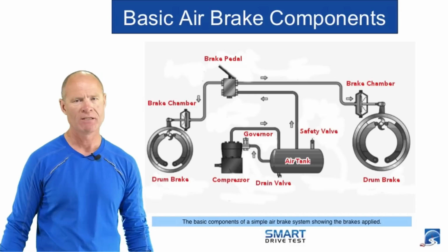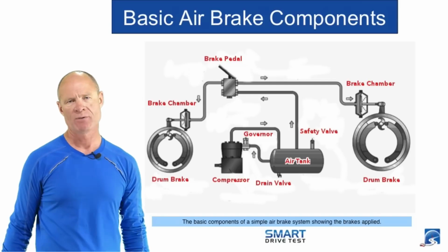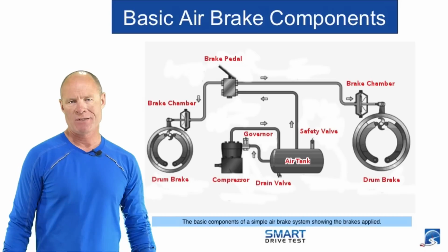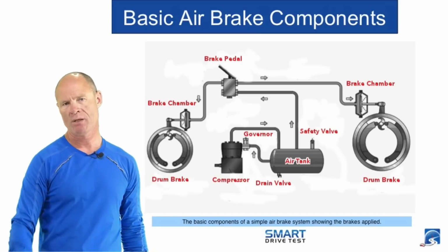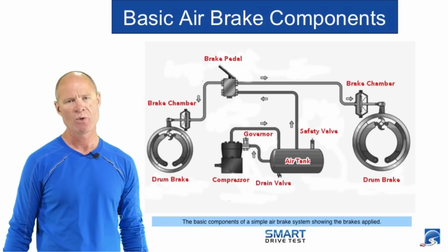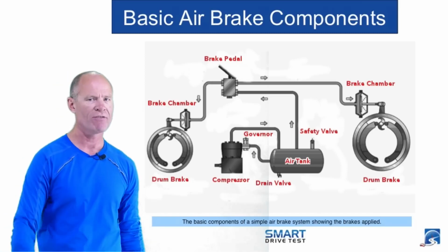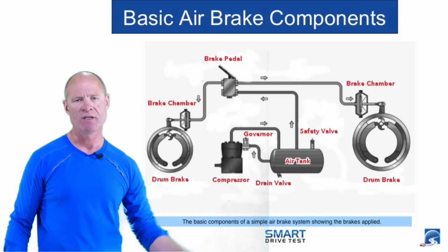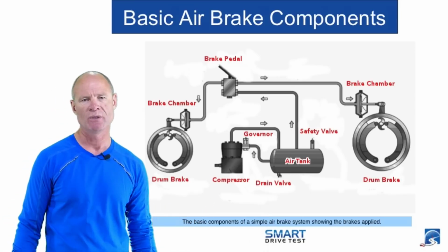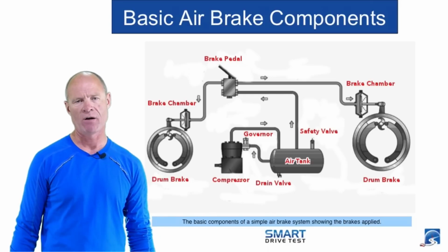Wedge brakes: in the 20 years that I've been teaching air brakes, I've only ever seen wedge brakes once, and that was on a trailer on the island, and it was kind of a novelty to take the students out and show them wedge brakes. The question on the test for wedge brakes is they may have 1 or 2 brake chambers. That's the question on the test. As well, to identify a wedge brake, the brake chamber and the push rod will be facing into the brake assembly as opposed to at a 90-degree angle as they are on drum brakes.